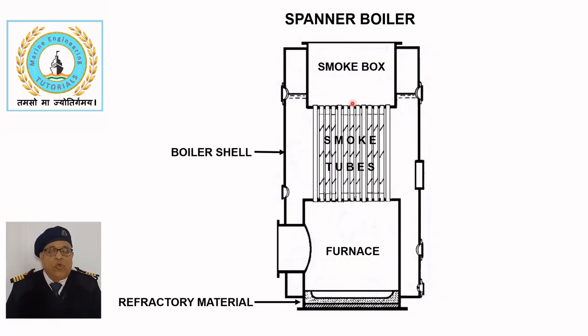The vertical smoke tubes are of a special design known as swirly flow tubes, which have a helical twist along most of their length and a plain section at both ends. This design improves heat transfer by increasing the effective surface area and promoting turbulent gas flow.